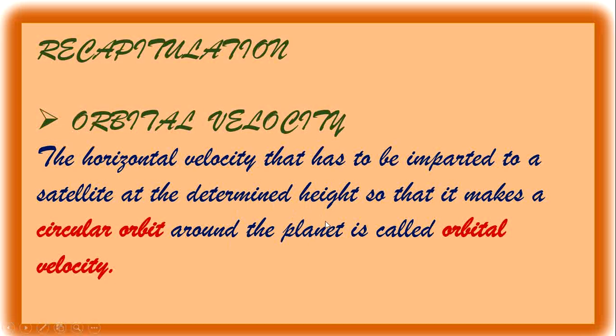This orbital velocity of the satellite only depends upon the altitude above the earth. If the object is very close to the earth, the faster is the required orbital velocity. At an altitude of 200 kilometers, the required orbital velocity is little more than 27,400 kilometers per hour.